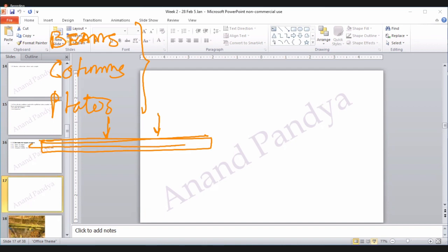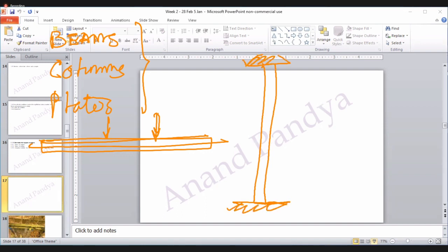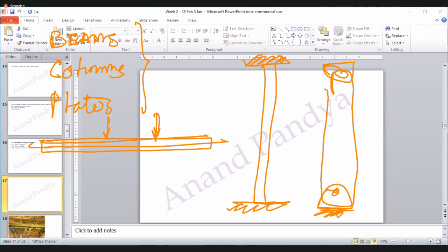This is the axis of a beam and the load is perpendicular. But sometimes slender objects are kept vertical, maybe fixed at one end or both ends. Again, this fixing can be in a variety of ways, both ends hinged, etc. Such things are called columns, or there is another name also, strut.